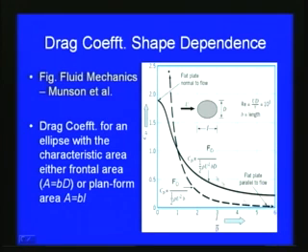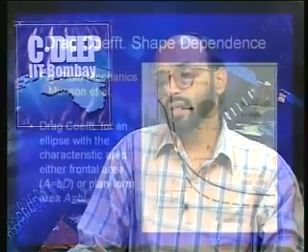That is why I mentioned that how you place the body over which the flow takes place matters. If it is normal to the flow, as we have seen for the flat plate, the drag coefficient will be much higher, and if you place the flat plate parallel to the flow, the drag coefficient will be much lower, as shown in this plot.